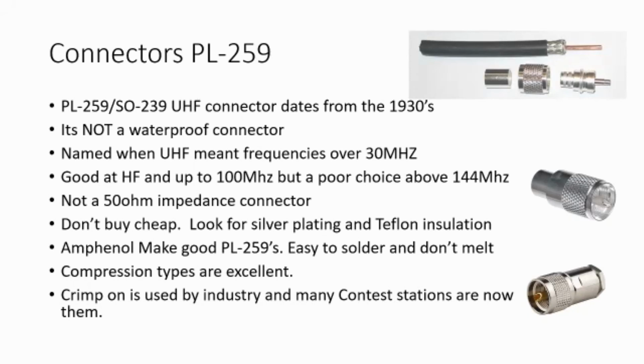What you want to look for is silver plating and preferably Teflon insulation. The Teflon insulation will not melt, and the silver plating is easier to solder to. Also, compression types are very good, and they are intrinsically waterproof if you put them together correctly.